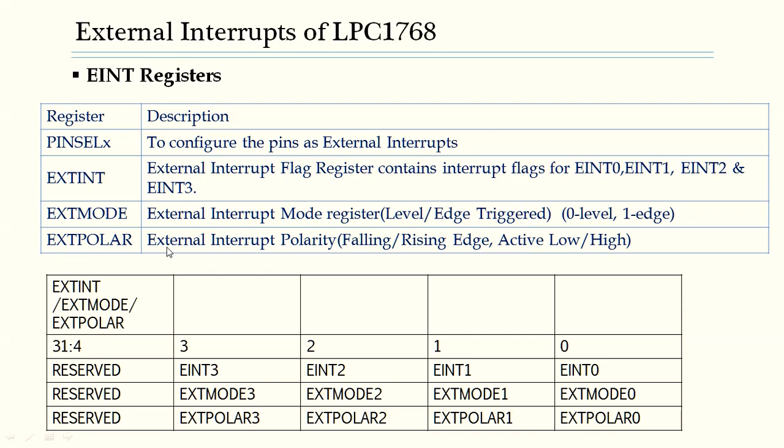On the other hand, if you say that the external interrupt mode is edge triggered, then what is the corresponding polarity? It can either be a rising edge or it can be a falling edge. So these two registers go hand in hand. Here is the description that we have given for all these three registers.